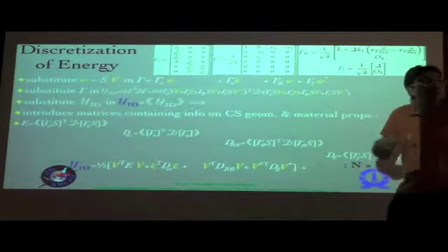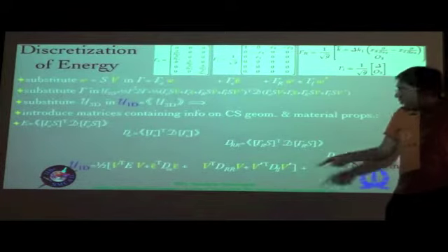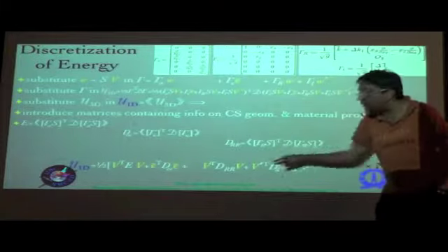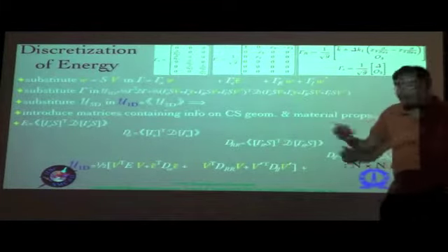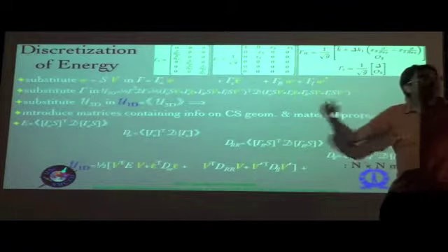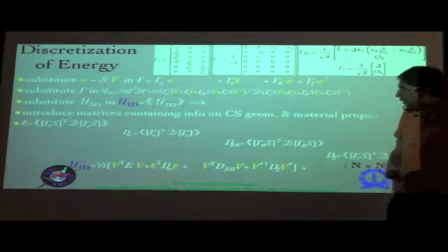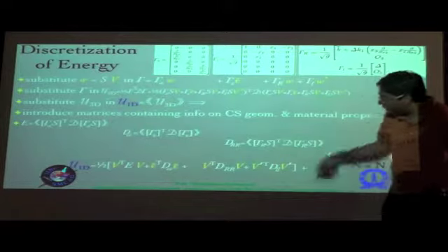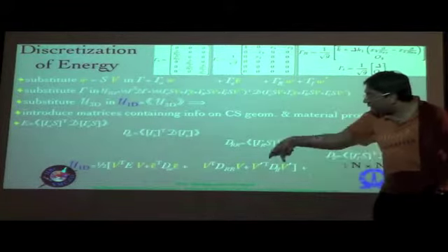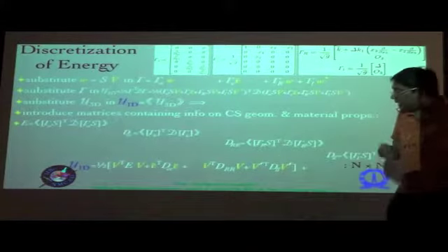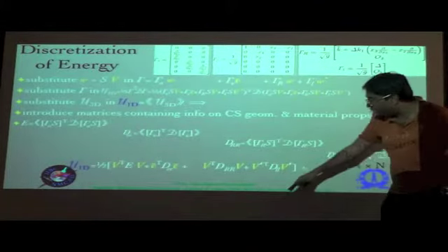Typically the contribution of this will be very, very small because this, remember, is a representative of the warping without the shape function, and basically that derivative with respect to x1, where x1 is a very large quantity, the length is large compared to the cross-sectional dimension, so it basically has a small contribution in general, but it can play a crucial role in some situations, as we shall see shortly.